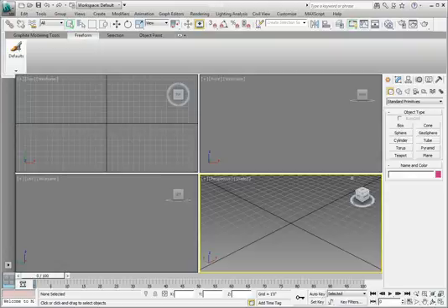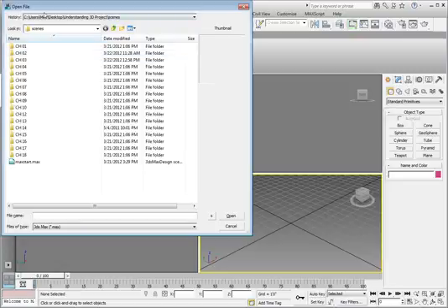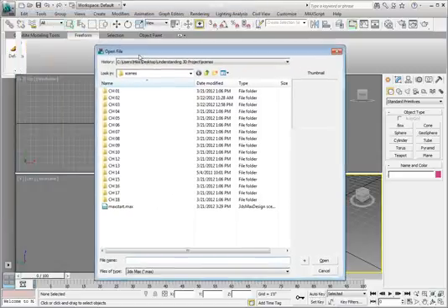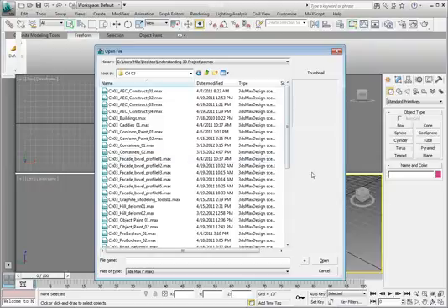In 3ds Max, click on the Application button in the upper left-hand corner of the interface. Select Open from the drop-down menu. Navigate to the Chapter 3 folder inside the Understanding 3D Project Scenes folder and open the file Chapter 3 conformpaint01.max.